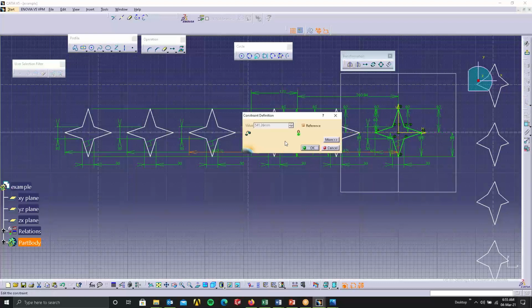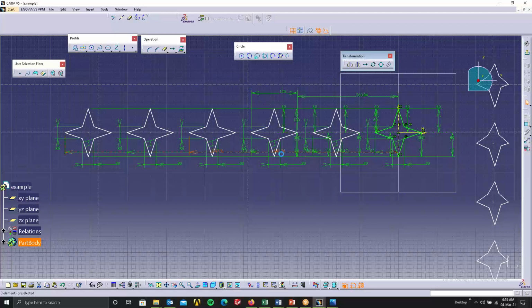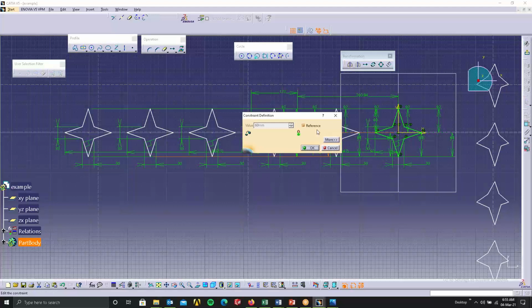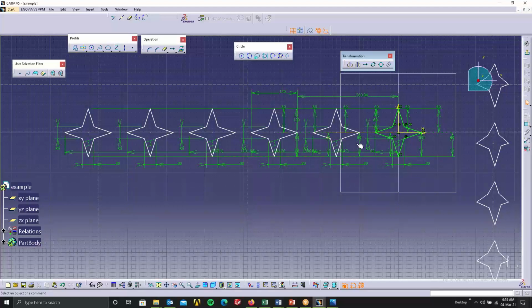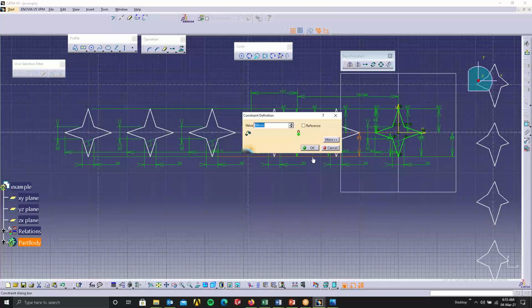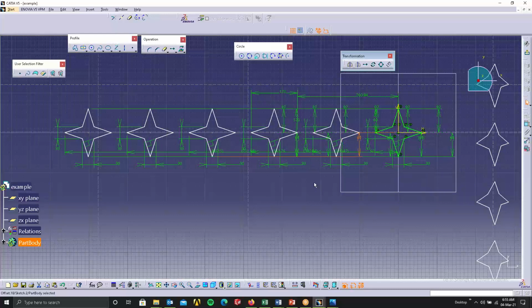because in most places what they have done is they have taken it as reference. So we don't want this reference. Once we remove this reference, it will become even more properly constrained. If it's reference, it won't do anything. It has no function at all. That's so much removed. Now it's almost getting there.